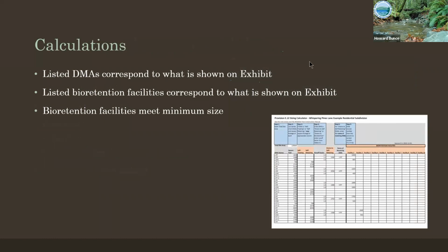Dan, we have a sizing question on treatment systems for bioretention. The question is, the current MRP allows for sizing criteria for treatments to follow the 3 sizing design criteria: volume hydraulic design basis, flow hydraulic design basis, and the combination flow and volume design basis. If BASMA is a guidance tool which strictly requires using a 0.04 sizing factor flow design basis to size bioretention, can the other 2 methods be used?